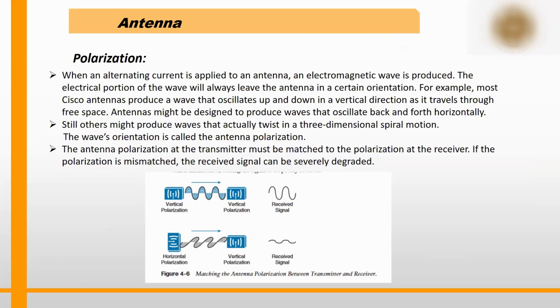Is the 4 dBi and 12 dBi gain fixed, or does it vary? Yes, it is fixed for omnidirectional antennas, but it depends on the manufacturer, the kind of materials that they use and all.